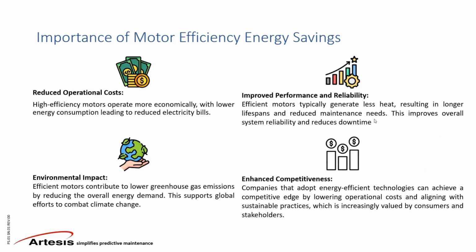But more importantly, less heat on the machine, since it becomes more efficient, results in longer lifespans and reduced maintenance needs, because when the motor gets hotter, the lifespan of the windings on the stator decreases significantly.